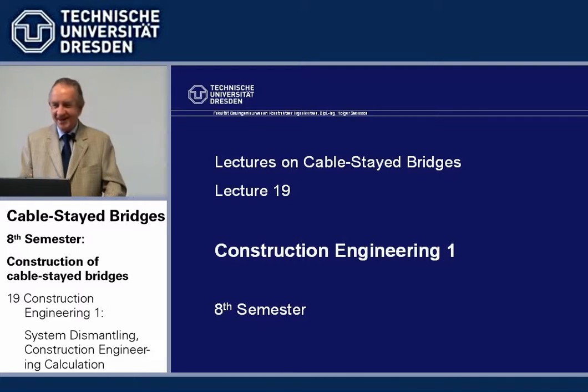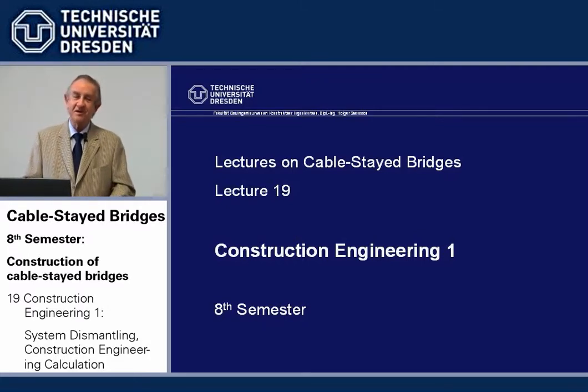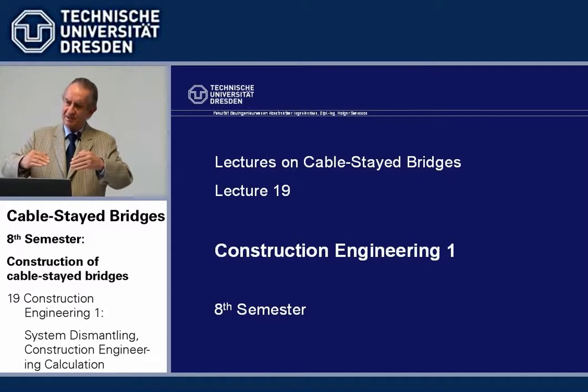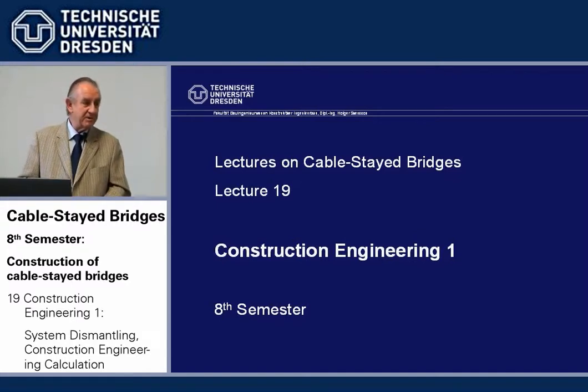And I had to do it, and with very limited computer systems at that time. Strudel isn't a program which is really fit for cable-stayed bridges, but that's all we had. And the numeric preciseness wasn't all that. So we had to do the all-important final stage by hand. And then Strudel couldn't add up changed systems. The system changes from one construction stage when we dismantle it to the other, and Strudel couldn't add up different systems.